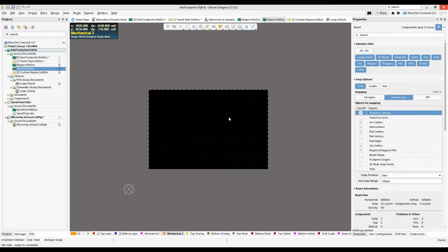We had a customer, remember, he was getting very frustrated because he was a mechanical engineer, learning Altium Designer, and I showed him how to do the 3D stuff. And he was like, man, they're all over the place. And I had to explain to him, look, if you're going to draw these things in your MCAD tool, then make sure you're very careful about where you put your origin. And right after he'd figured that out, all this stuff would just land perfectly within Altium when he was trying to do his 3D. But most of us don't think that way.